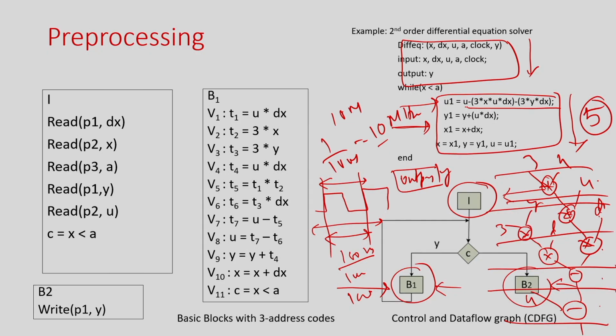Now the question is, there are so many multiplications here, so let us say I decided to do it in 5 clocks, right. In the first clock, what operations am I going to do, in the second clock, what operations, in the third clock, and so on? It cannot be random, where I just put this operation here and there, because in that case your functionality might change, right.